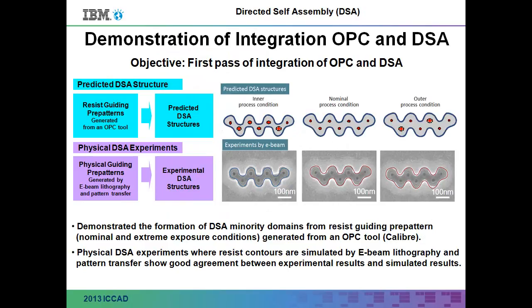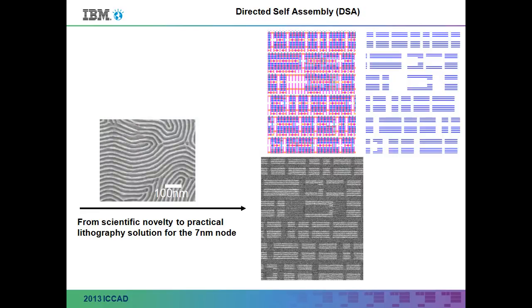You can also do this for vias, right? It's not just a 1D situation. If you have a more interesting guide pattern, you can get via-type shapes to self-assemble within these low energy states. I'm still a little skeptical on whether we can actually get the placement of these vias good enough to hit the wires at the dimensions we need, but there's a lot of very interesting work going on here in directed self-assembly. So it's like I said, kind of chemistry magic here.